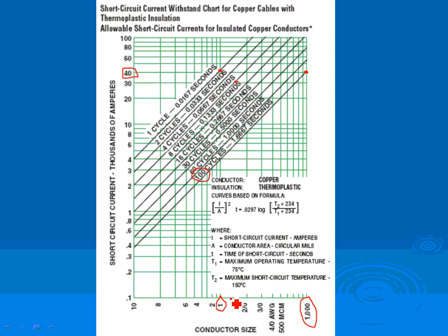That drives a lot of people nuts. For the same load. Because you size based on the full load current and also the withstand rating of the conductor. If you have a short circuit, you need to make sure your conductor is not going to burn. Any comments, guys? Any questions?